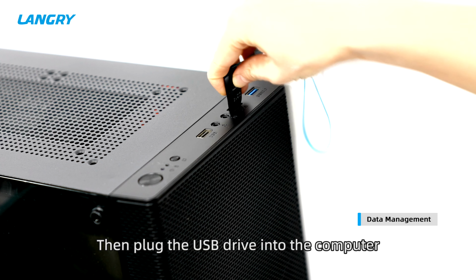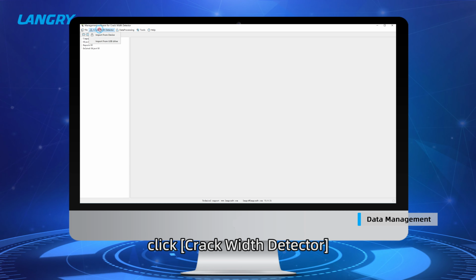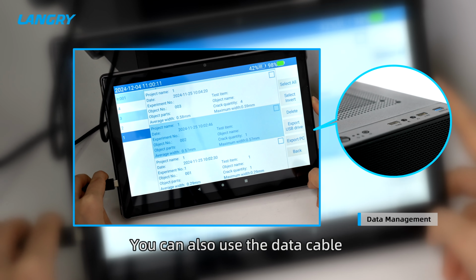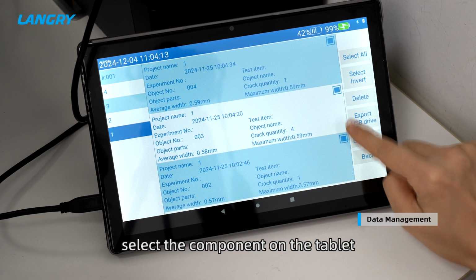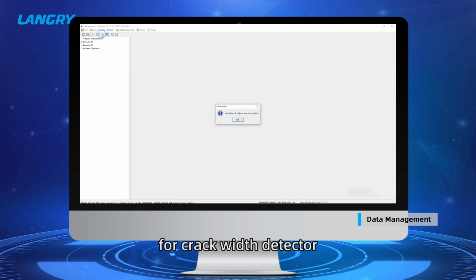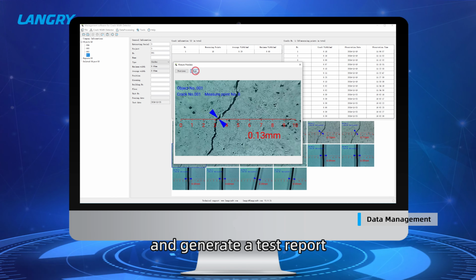Then plug the USB drive into the computer. Open the online system management software on the computer. Click Crack Width Detector. Click Import from USB drive, and you can import the data into the software. You can also use the data cable to connect the tablet to the computer. Select the component on the tablet, click Export PC, and then click Import from Device, and the computer management software for Crack Width Detector. You can also import the data into the software. And then you can process the data and generate a test report.